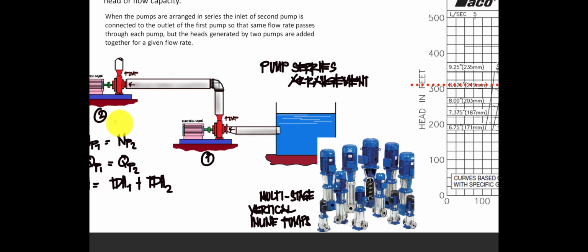So if you have 4, basing on this type yung arrangement natin, going back yung pump 1, pump 2, mapapansin nyo, we have here 1 and 2. Then your TDH mo nito, ang mangyayari, it will be equal to the total dynamic head of your impeller 1 plus the total dynamic head of your impeller 2 plus impeller 3, and so on, until you reach the 4. So that will be the total dynamic head ng pump na ito, at the same RPM, and also at the same volume flow rate. So yung volume flow rate mo, constant, but yung total dynamic head mo increases per staging.